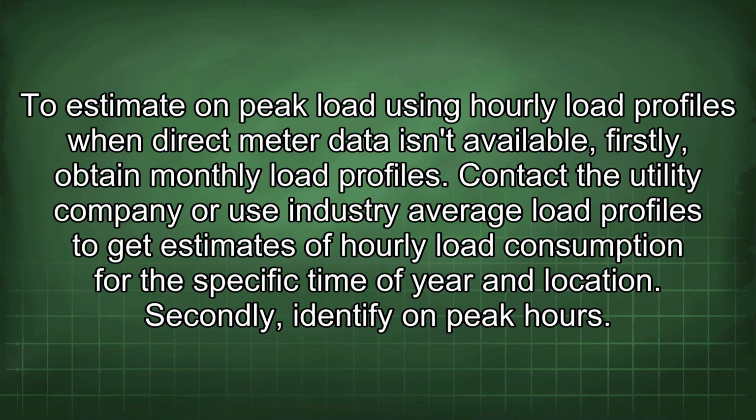To estimate on-peak load using hourly load profiles when direct meter data isn't available. Firstly, obtain monthly load profiles. Contact the utility company or use industry average load profiles to get estimates of hourly load consumption for the specific time of year and location.